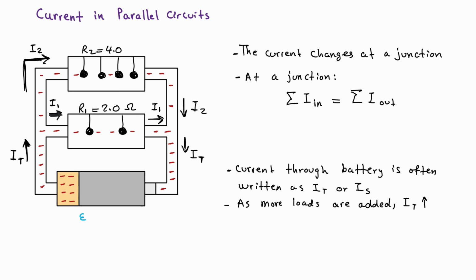So let's say the EMF here is 12. And based on the last slide, we learned that the voltage here, V1, will also equal 12, and the voltage here, V2, will also equal 12, because charges will come in with 12 and lose 12. These charges that go through this path come with 12 and they lose 12. But the potential difference here will equal the current multiplied by the resistance. So I'm just going to do the calculation. We'll do some examples a little bit later.